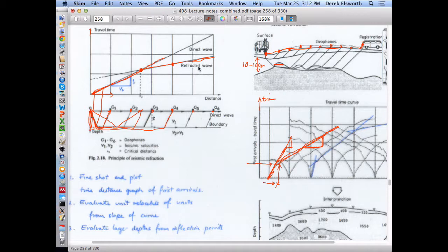In this case, if you do a height of 1 and the length of whatever it is, the seismic wave of material 2 and of material 1, this is 1 in each case. So the acoustic velocity in this lower material that it's going through is larger because this line here is larger than it is here. And so the two pieces of information are you get a magnitude of the velocities of the two layers from these slopes of these curves, which is this and this here.